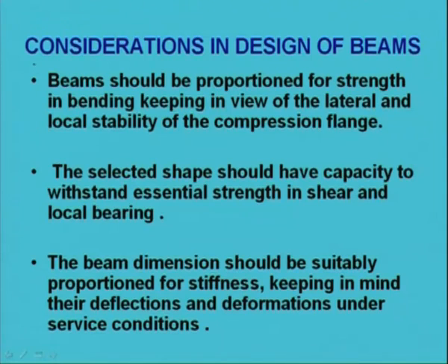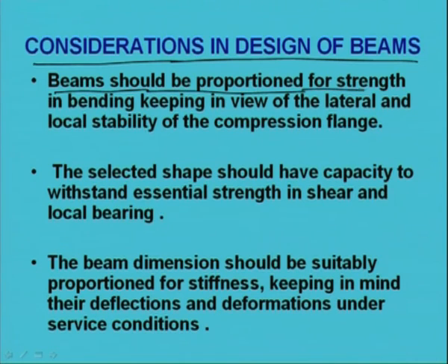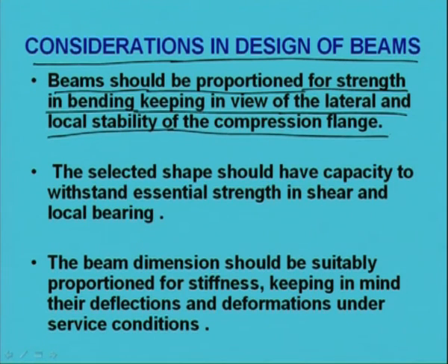Now, considerations in design of beams. First is, beam should be proportioned for strength in bending, keeping in view of the lateral and local stability of the compression flange. The selected shape should have capacity to withstand essential strength in shear and local bearing.